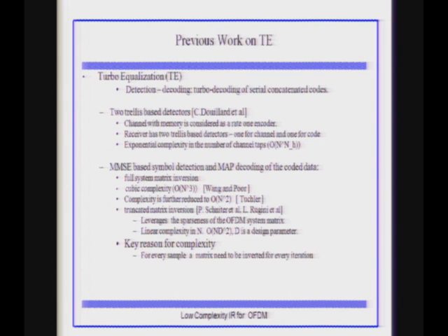Now that complexity was not acceptable for practical implementation, so people have been thinking further. Instead of this, how can we replace the rate 1 encoder idea of the channel with something else? And then came the MMSE linear filter idea. Instead of this idea, they replaced the channel with an equalizer.